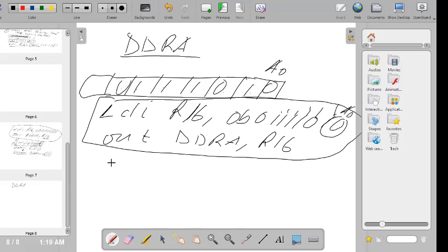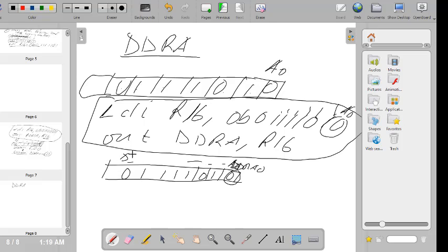So when you do that, it means that the information is now packed from 0 or maybe 1, then 0, then 1 1 1 1, something like that, 0. This is A0, or in short, this is DDRA0. So this will represent port A0 as an input port, and we have DDRA7. And this is exactly how you are able to affect the direction as well as the status of a port just using one register.